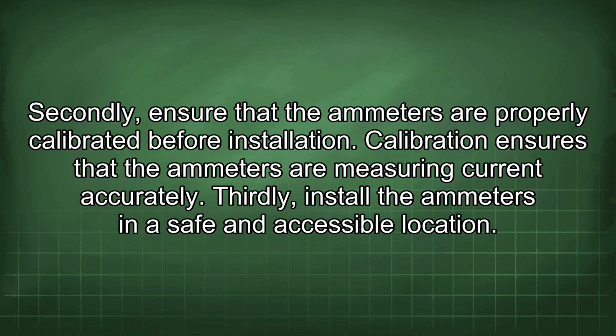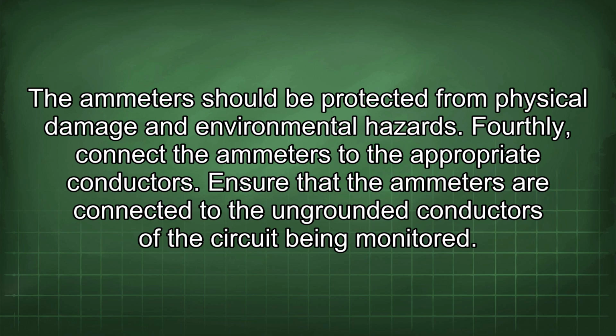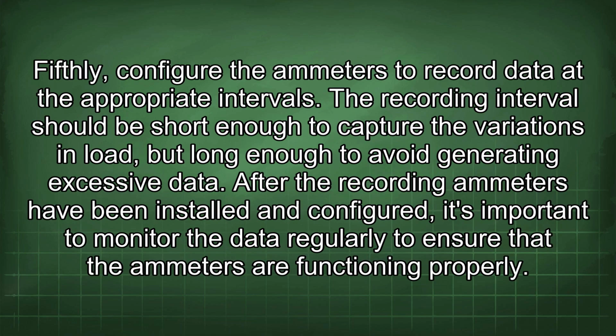Thirdly, install the ammeters in a safe and accessible location. The ammeters should be protected from physical damage and environmental hazards. Fourthly, connect the ammeters to the appropriate conductors. Ensure that the ammeters are connected to the ungrounded conductors of the circuit being monitored. Fifthly, configure the ammeters to record data at the appropriate intervals. The recording interval should be short enough to capture the variations in load, but long enough to avoid generating excessive